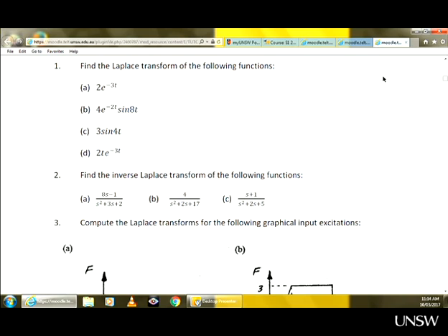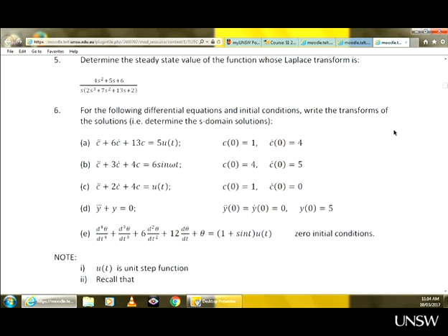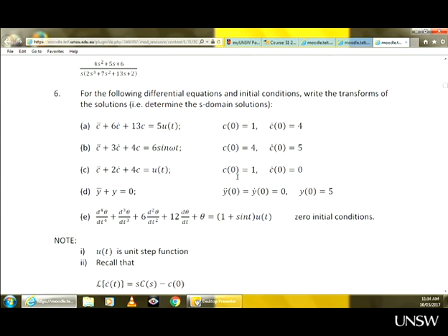So when you were doing set 2, down here we said, for transfer function, ignore initial conditions. When you're solving these problems, if you want to find the output, you have to include the initial conditions. If you want to find the transfer function, you assume they are all zero. But this is an example of how I do it. I don't just say they are zero. I say room temperature is my reference temperature, my datum temperature. Therefore, I call it zero.